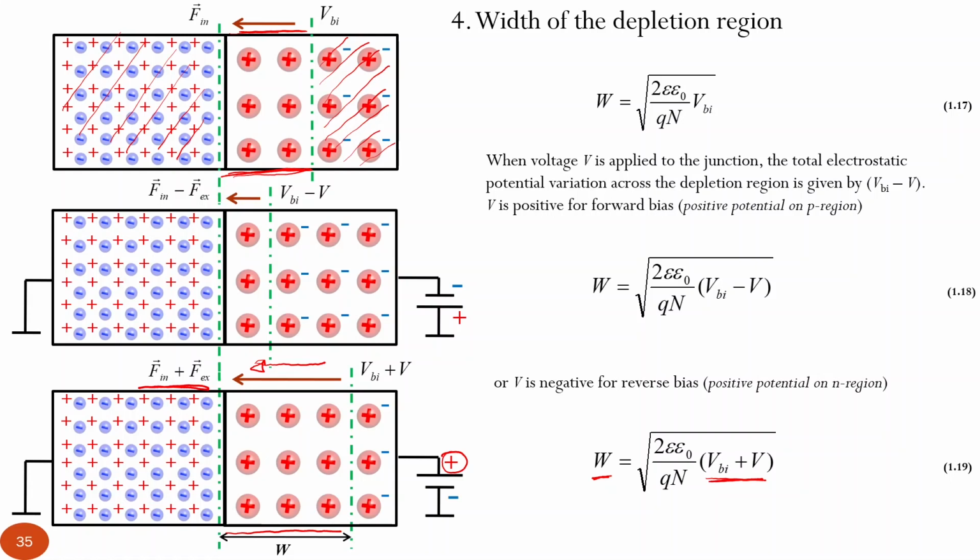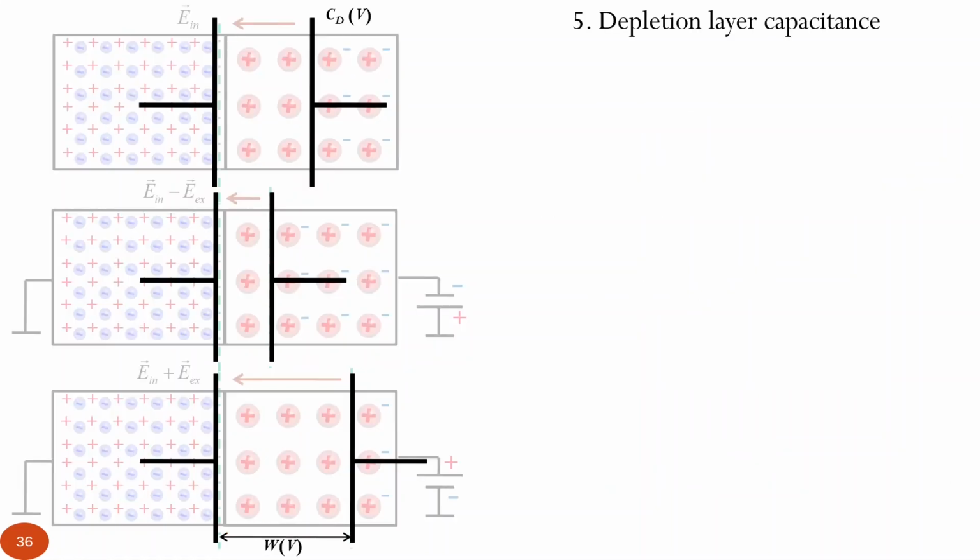So that is actually a capacitor, but as opposed to a parallel plate capacitor, which you commonly deal with, one of the key parameters, the thickness of the capacitor, is not constant here, because as you see, the thickness of this depletion region, means region with high electrical resistance, is bias dependent.